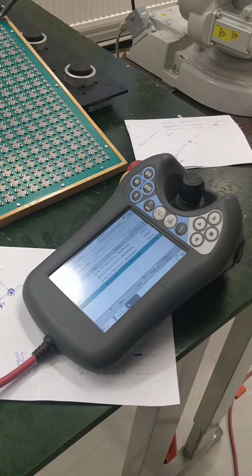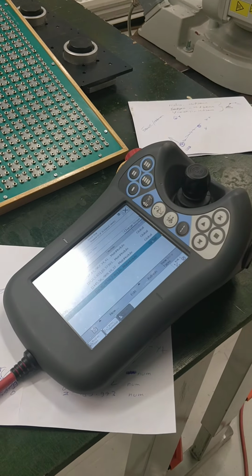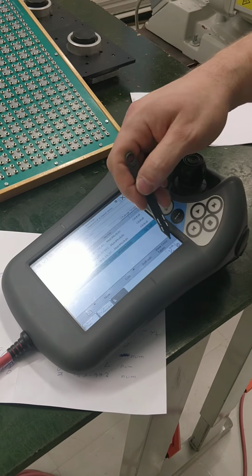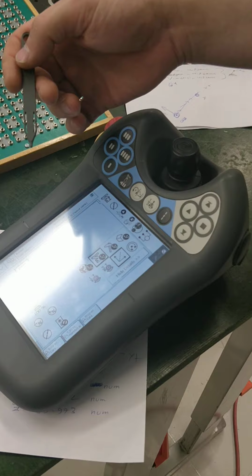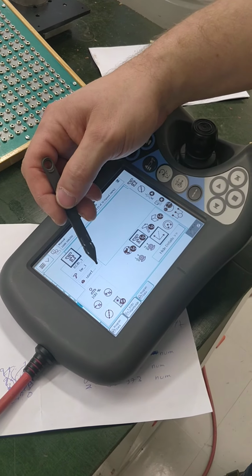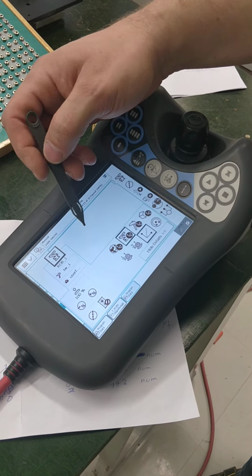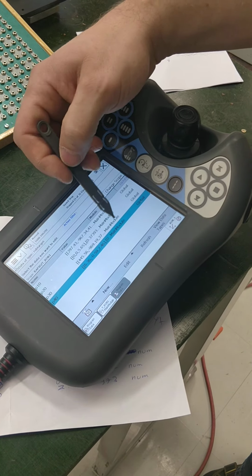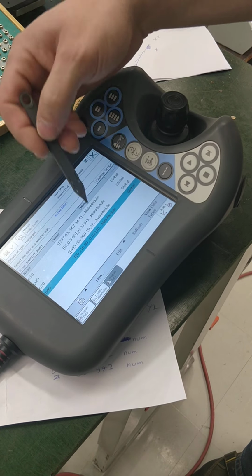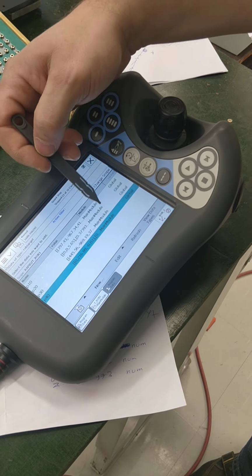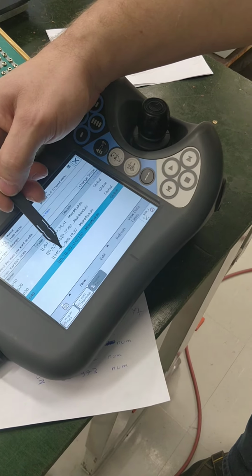Now I go to a different program data page. Now I see that there is my P40. I go there and pick that I now use my own user frame, because I have to make that coordinate inactive. And then I go to program data. Now I see that P40, edit, modify position, modify. X should be 0, like it was, but my Y direction 260, and my Z will also be 0. I am only in the Y direction, 260 millimeters.